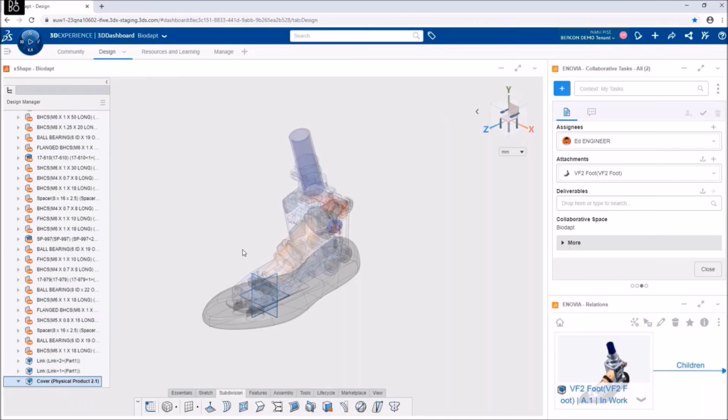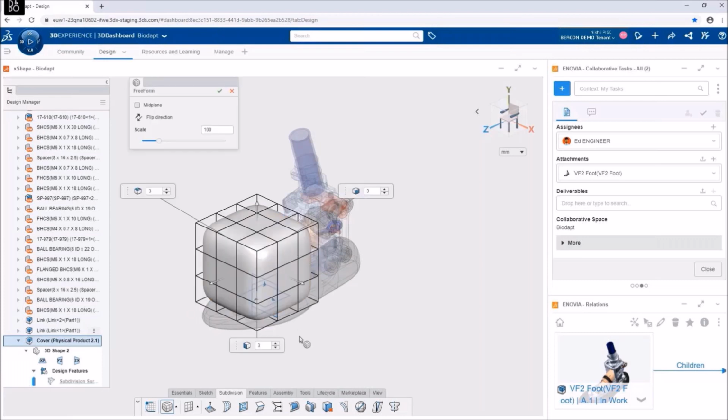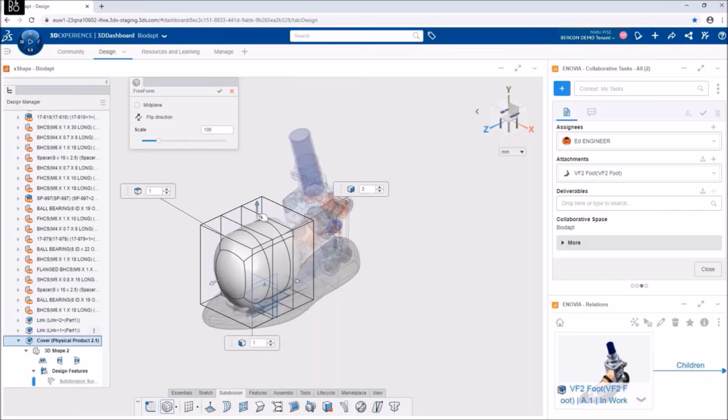So here I can directly use some primitive shapes. I just drag and drop onto the required location, and I just need to push and pull, as in a clay modeling technique. Primitive shapes like box, cylinder, globe, torus, and cones are present. For my requirement, I'm using the box. I'm placing it at the origin, and there are multiple subdivisions in different directions. As per requirement, I am adding the subdivisions. I can scale it by pulling and pushing the handle.